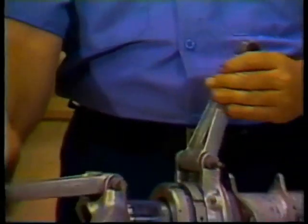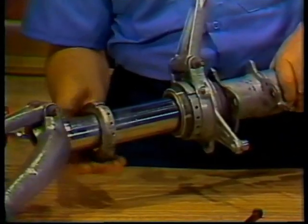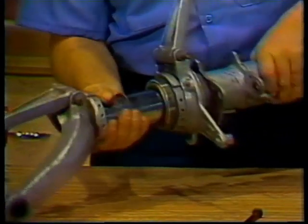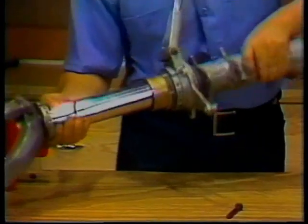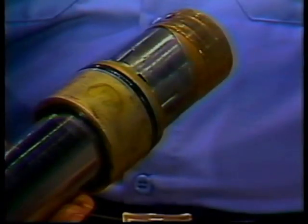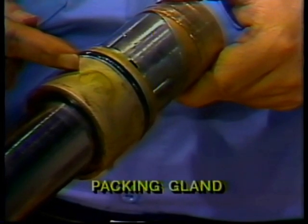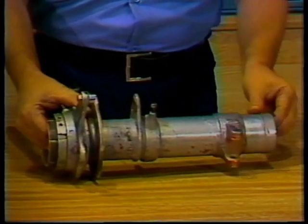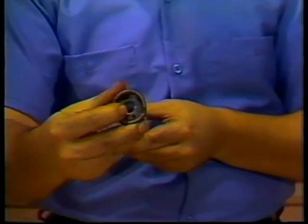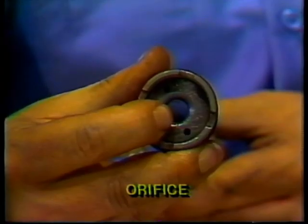A packing gland designed to seal the sliding joint between the cylinder and the piston is installed, and a packing gland wiper ring is installed in the lower bearing gland nut to keep the sliding surface of the piston free from dirt, ice, mud, and snow. Foreign material entering the packing gland could result in leaks. An orifice is placed between the two chambers to provide a passage for fluid into the upper chamber during compression and a return path during extension of the strut.